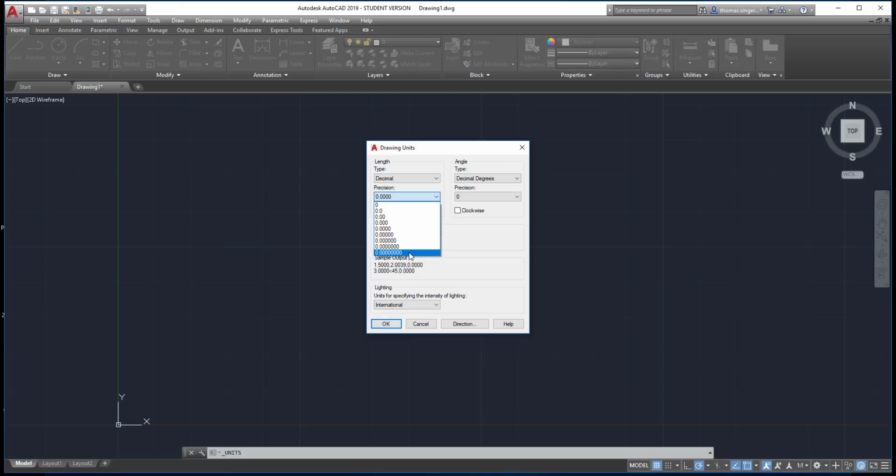They're typically temperature, humidity, human controlled, meaning no humans can interact directly with the creation tools, because as we walk into a room, our body heat could change the size of the part when you're dealing with 8 decimal places. Or if we touch it, it definitely will change the size of the part. So in most cases, everybody works with 2 or 3 decimal places or 4, but 2 is the most common, and then it works up from there.